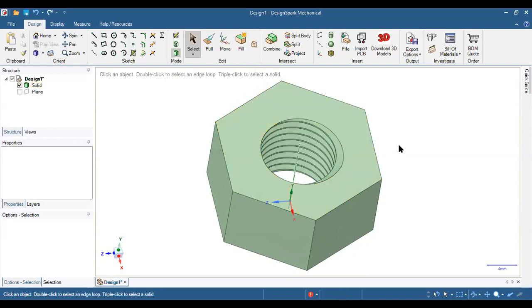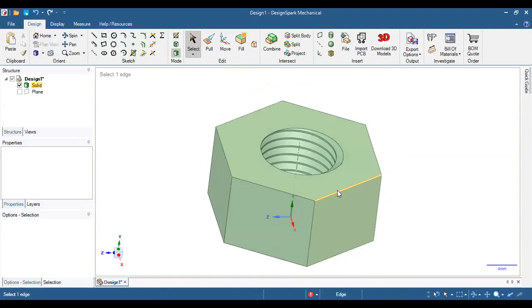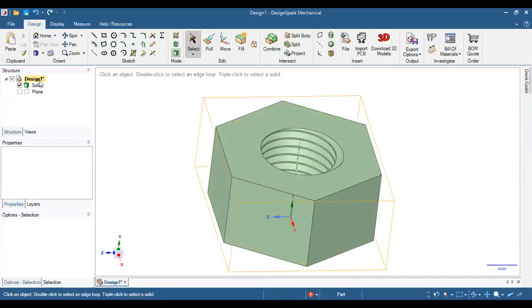Okay. So this way we have defined the chamfering, and the chamfering must provide the strength and smoothen the corner sharp edges of the hexagonal nut, or the hexagonal bolt head. So that's why we are using the chamfering. So in this case, to define the chamfering, I'm going to insert a new component.